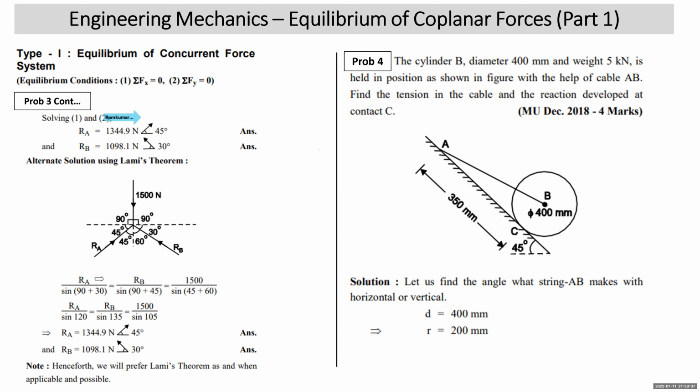So at this stage, you'll realize that use of Lami's theorem is quick, fast, and it is liked by the student, but we should always make sure that whenever it is applicable, then only we should apply it. It is not applicable when we have more than three forces. And direction of unknown should be known. No angle should exceed 180 degrees. Otherwise, it is not. In spite of so many limitations, Lami's theorem is a very useful theorem. We will use it as and when it is applicable. So in subsequent problems, I'll always use Lami's theorem as and when it is applicable.